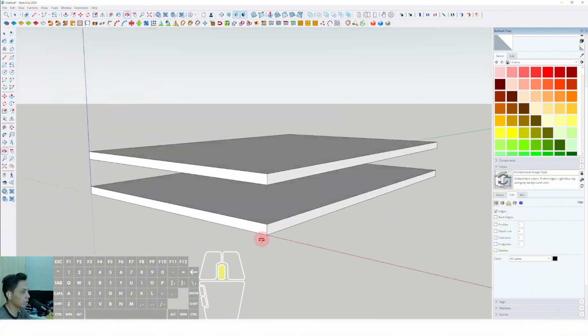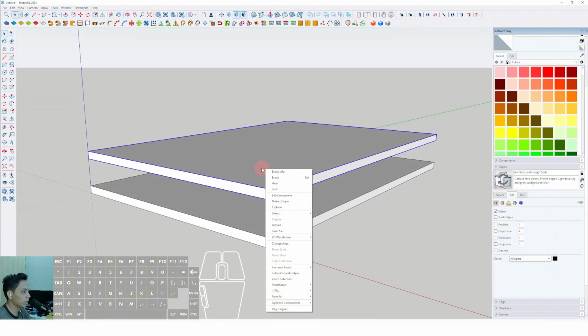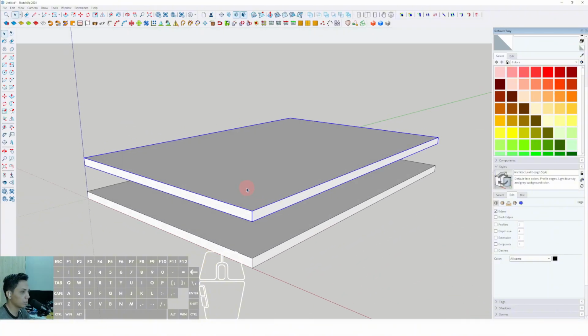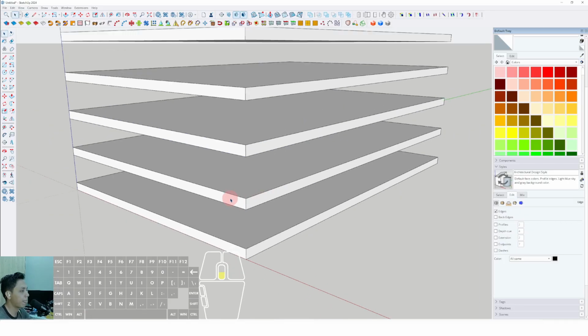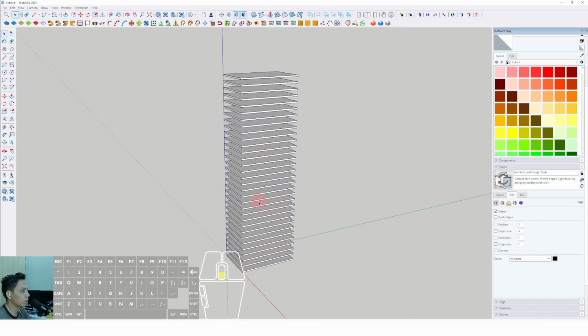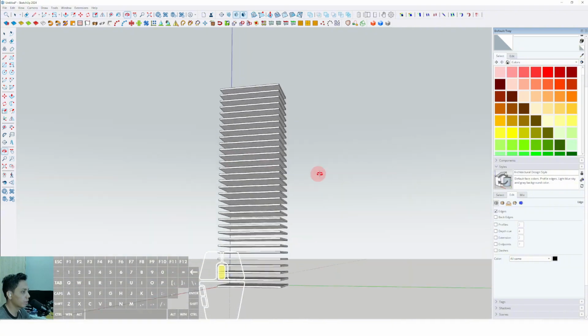Okay, then we've already made it unique, and now we can select this object, select move, press Ctrl just once on our keyboard, click from this corner to this corner, and we can type X30 and enter. Okay, well, now we can get the result of it.